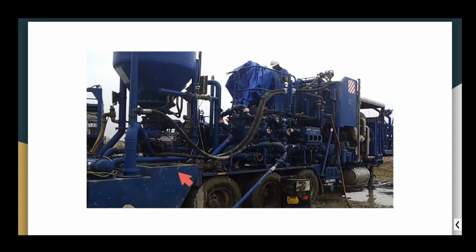This pipeline goes directly to the recirculation centrifugal pump, and then the mixing process is started, and also this recirculation again while slurry goes through the densitometer right here. The operator can measure the level of density on the dashboard, and then circulate again here.